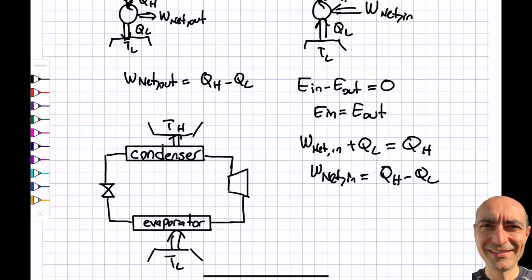And there's another thing called the heat pump, and the heat pump is operating AC in a reverse manner, okay? So what happens is, this is at colder temperature. This will be inside of your room. Outside will be cold, inside will be hot, but I still want to put even more heat into it, right? I want to keep it hot. So what I do is I take heat from the outside evaporator and run it through this cycle, and I put heat into my room. Okay, so that's the heat pump versus the air conditioning or refrigeration system.